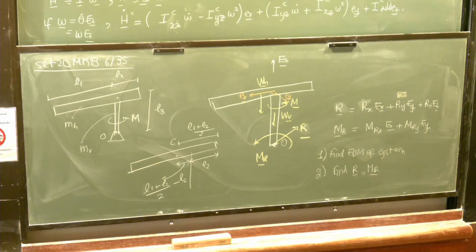Take a pen, hold it up top. So if I push the pen with a strong force from below, like this, where do you feel the reaction force at the top of the pen needs to be? In which direction, so that it doesn't go? I feel like the pen is tending to move this way, so the reaction force needs to be that way. However, if I strike it up here, what is the direction of the reaction force going to be? Opposite, because the end of the pen is tending to move in this direction, so my reaction force is going to be in the opposite direction.